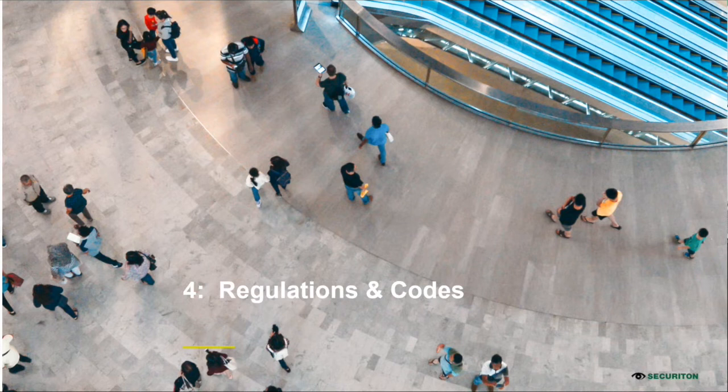And does the system check the healthiness by any mechanism, or how can we know that there is a problem in the pipe or in the unit? Yeah, so you can get to know locally also on the screen of the ASD. We have different LEDs which show you the fault signals, and this ASD, aspirating smoke detector, if it is connected to a fire alarm system, you will get the same signals replicated on the fire alarm panel.